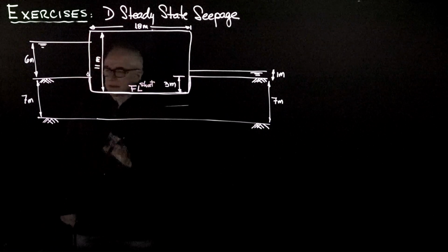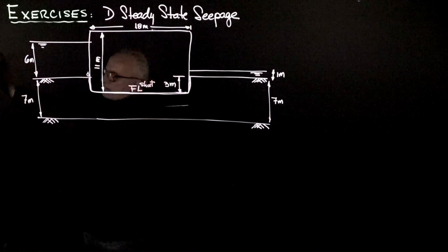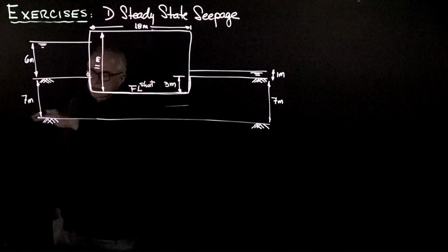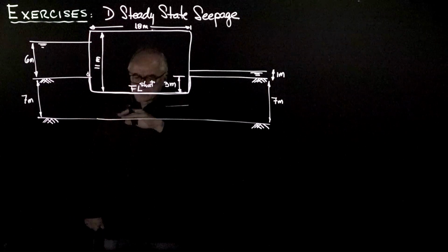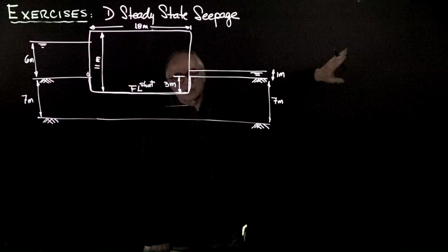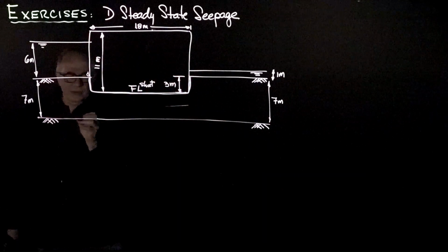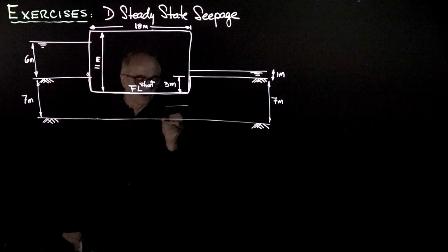On the other hand, if I place a drop of ink all the way upstream, that one will sink in and will come along this lowest boundary all the way until it exits all the way in the far right. Therefore, this lower line has to be the longest flow line.